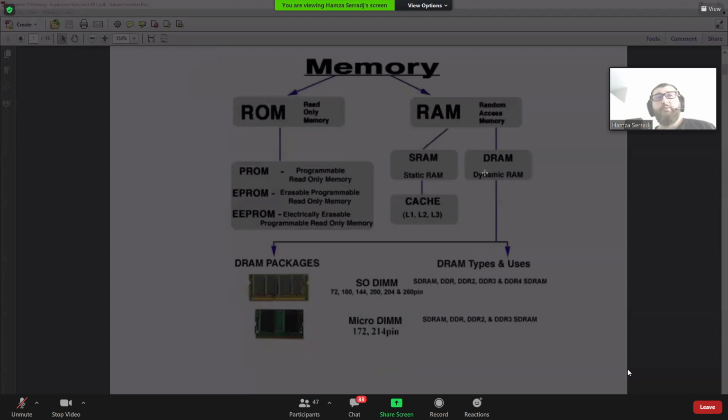Which one consumes more energy than the other one here between the DRAM and the SRAM? DRAM, be careful. Ankush, it's not SRAM, it's DRAM. The DRAM needs continuous refresh. Remember, guys, even to do nothing, just to keep the data inside, we need to refresh that RAM.